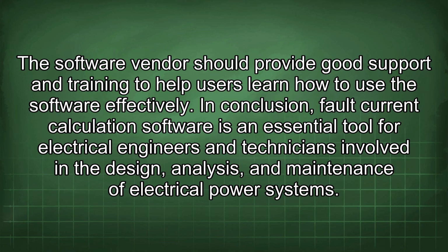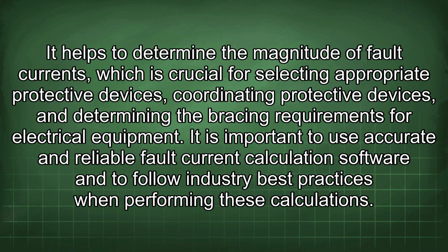In conclusion, fault current calculation software is an essential tool for electrical engineers and technicians involved in the design, analysis, and maintenance of electrical power systems. It helps to determine the magnitude of fault currents, which is crucial for selecting appropriate protective devices, coordinating protective devices, and determining the bracing requirements for electrical equipment.